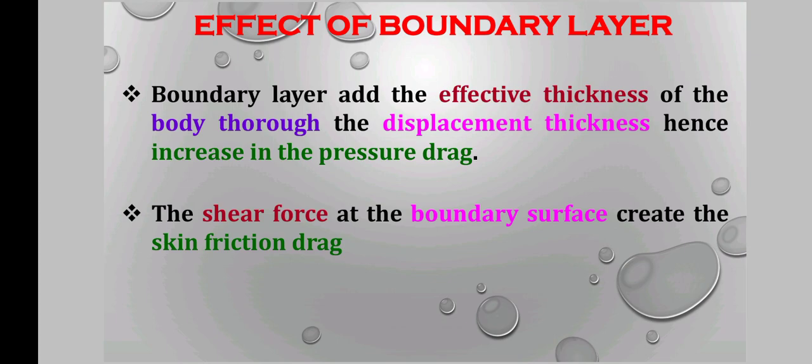Effect of boundary layer. Boundary layer adds to the effective thickness of the body through the displacement thickness, hence increasing the pressure drag. The shear force at the boundary surface creates the skin friction drag.